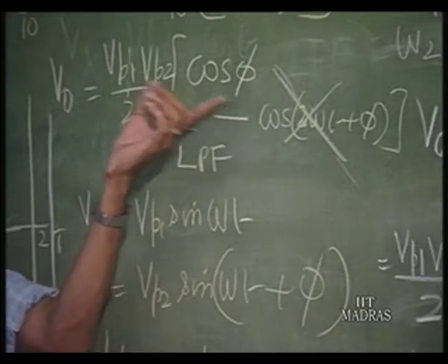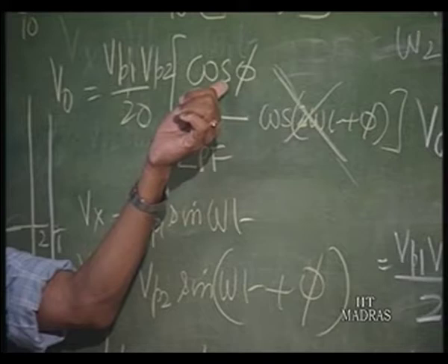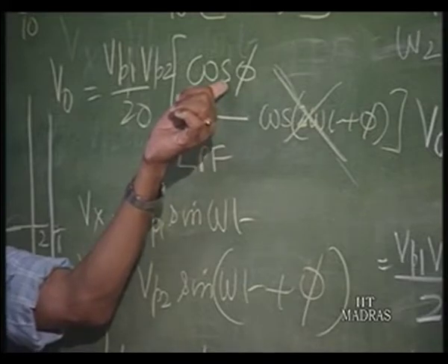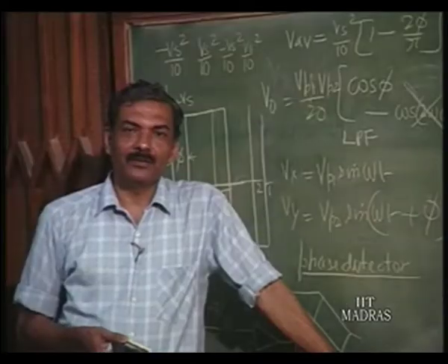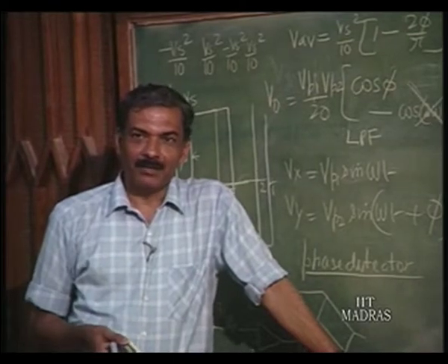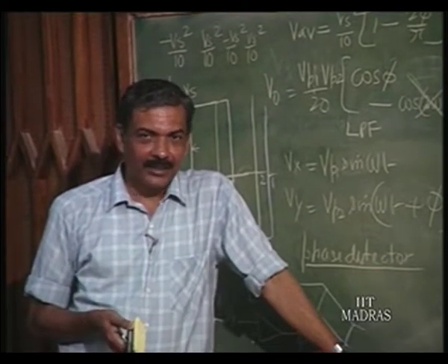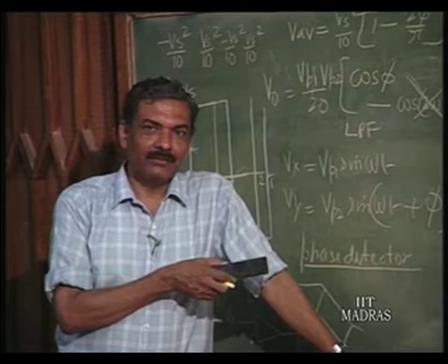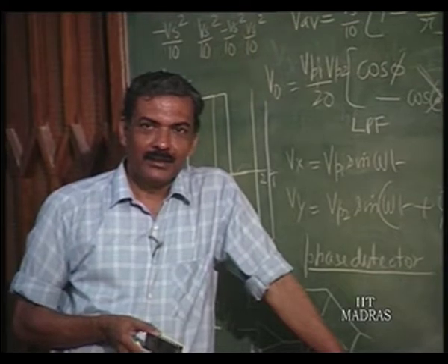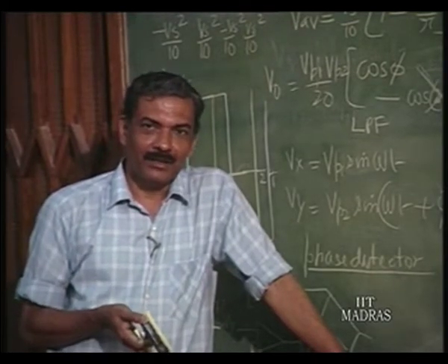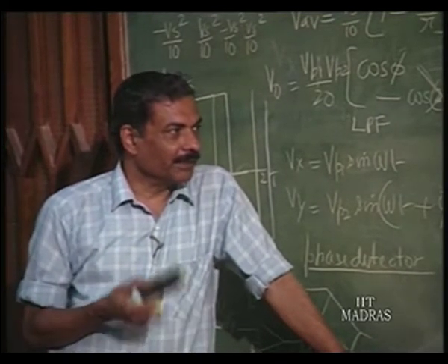If you use the amplitude information, it is nothing but the power consumed in the line. You can use this as a direct replacement of the 2 wattmeter method of power measurement. The 2 wattmeter method in a 3 phase circuit can be translated in terms of 2 such multipliers being used to evaluate the power of the 3 phase circuit. So, it can be used as a wattmeter.